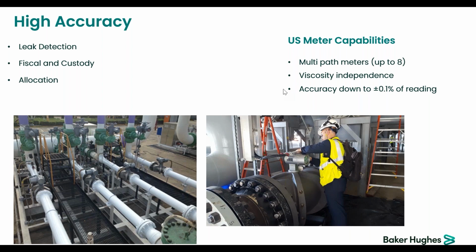Because we're on the slide of high accuracy, if you are on a physical measurement, the answer is yes, you do. If you're on a flare line, because you need to comply with some of the regulations, especially in the United States, it's not a calibration per se, it's what we call a verification, because calibration means that you compare versus a traceable reference that is certified. It's more a verification because it's not practical to calibrate a flare meter. So in this case, I would say yes again.